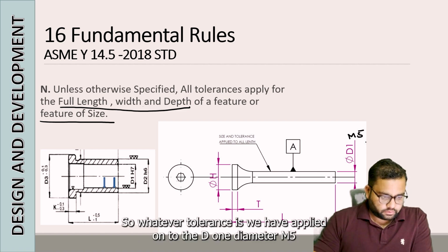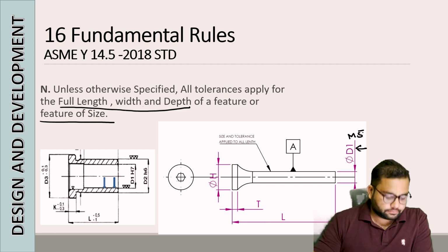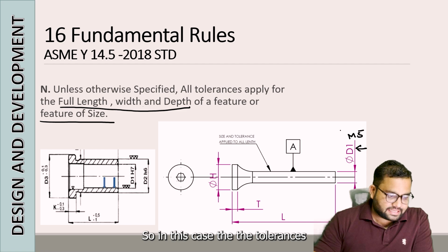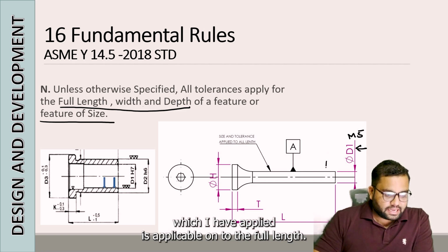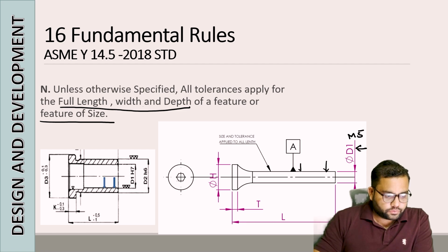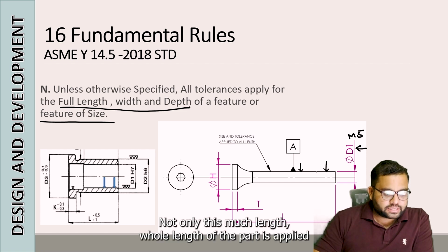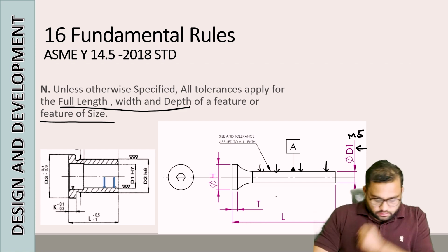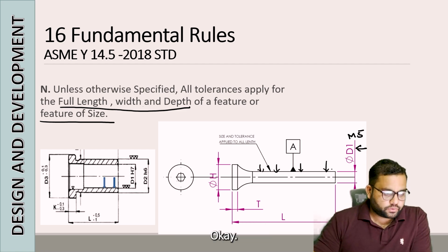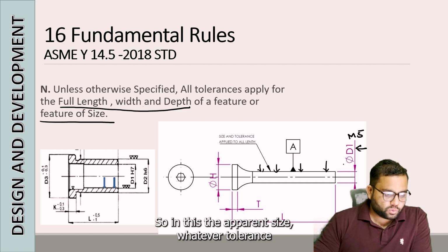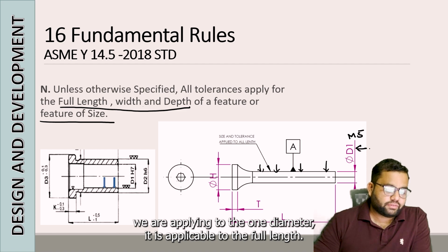The tolerances we have applied to the D1 diameter apply to the full length, not only this much length but the whole length of the part.